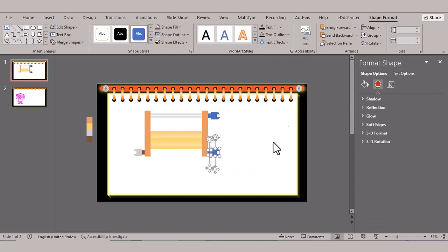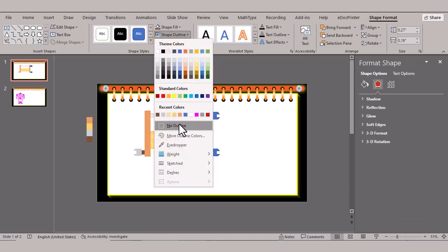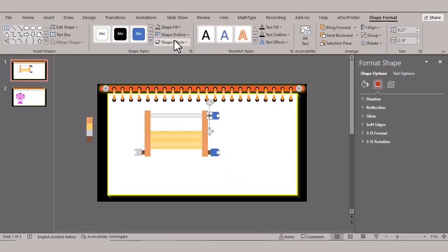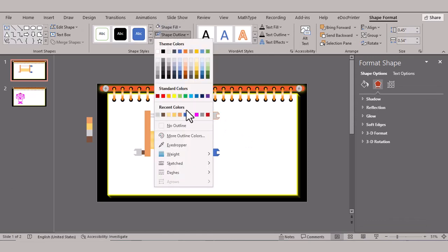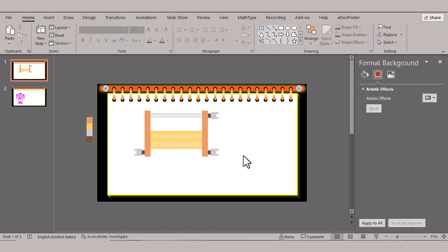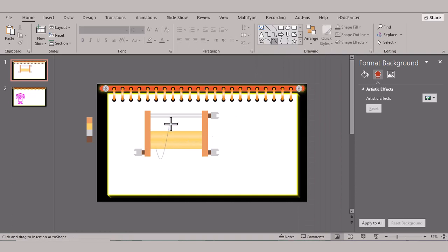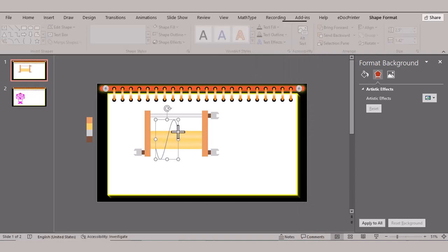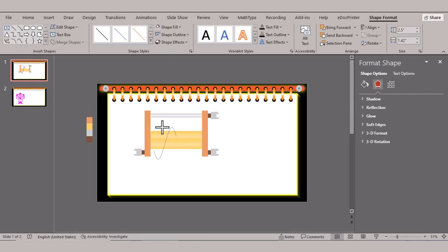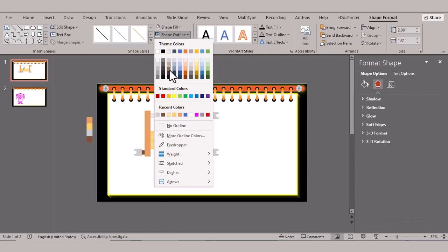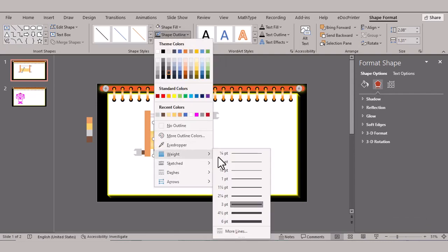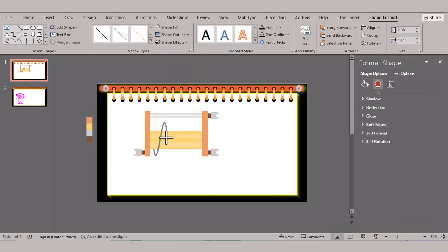To answer the question how do rheostats work, it is important to understand how to wire a rheostat circuit. We need to highlight the role of the terminals and connections on the resistor. A potentiometer uses 3 terminals, 1 at each fixed end, and a third connection at the sliding contact or wiper. A rheostat uses just 2 active terminals, one of which is fixed to either fixed end, the other can be left alone or grounded, while the second is connected to the wiper. As such, a potentiometer can be made to function as a rheostat by disconnecting one of the fixed terminals. A rheostat, however, cannot be made into a potentiometer by reversing the process.